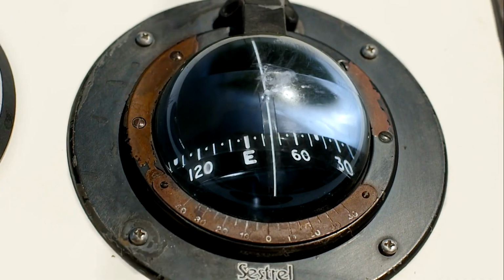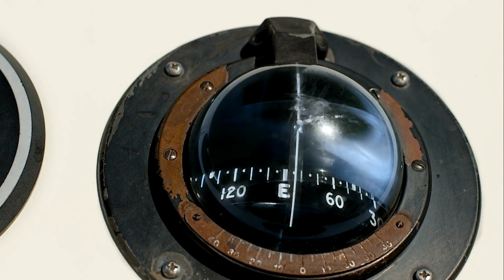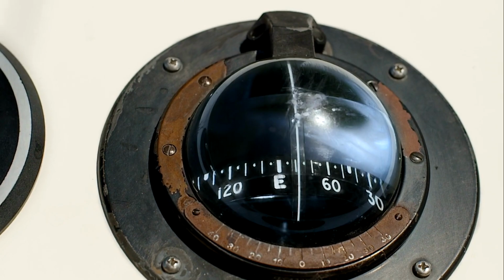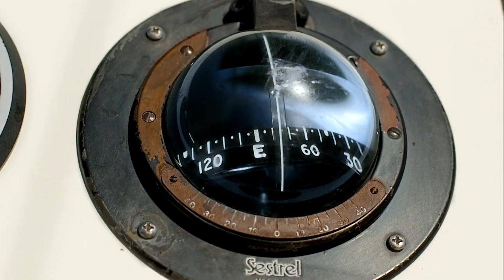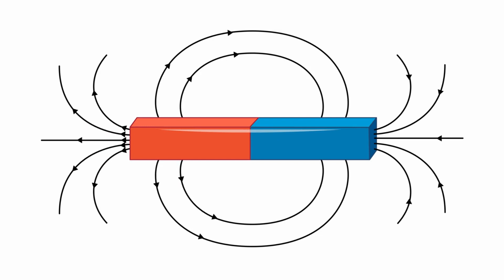Of course, it's going to be pretty hard to steer a course that accurate, but it's worth knowing how to work it out properly, as your navigation teacher is going to want to see an accurate number, not just a hazardous guess. If the variation is west, the North Magnetic Pole lies to the left of the true North Pole. If it is east, it lies to the right of the true North Pole.